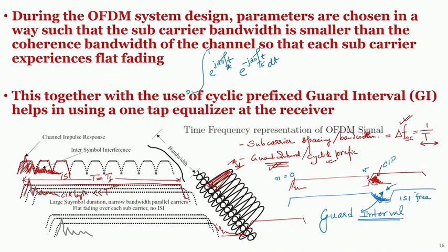impulse response. So, orthogonality can be brought in if we bring this channel impulse response into the picture. If we bring this channel impulse response into the picture, then we must also have a convolution with the channel impulse response as the basic signal, and overall we can bring in an orthogonality, but that would mean that this channel impulse response information is required at the transmitter. It requires to be available at the transmitter. So, that being made available and then being used kind of makes things very difficult. That is one of the aspects.